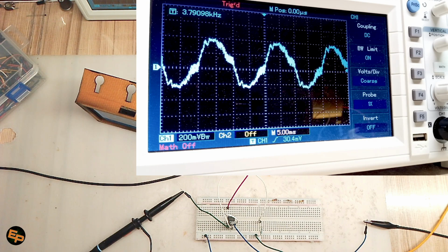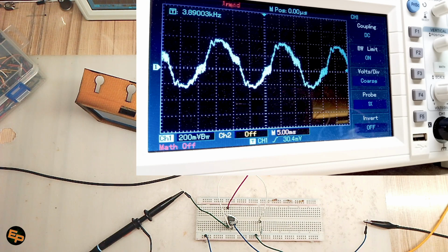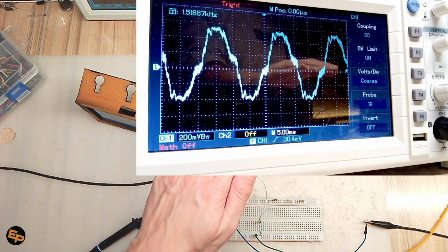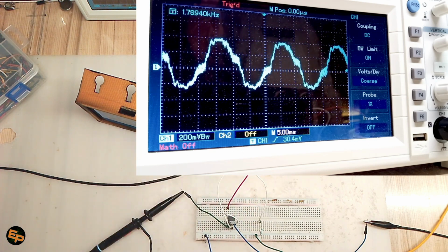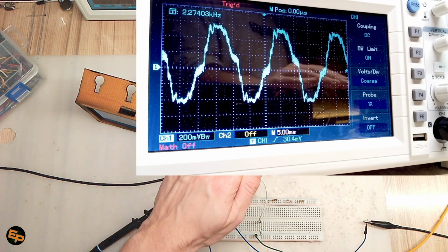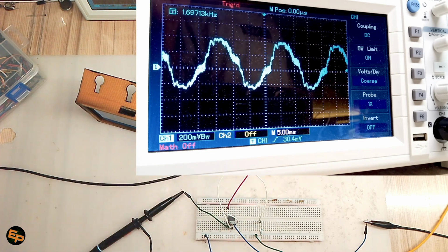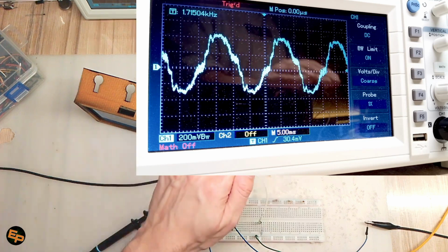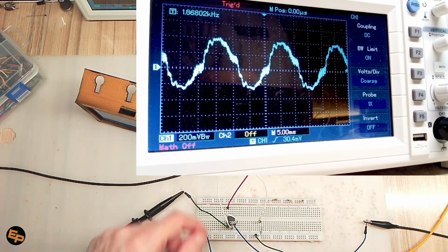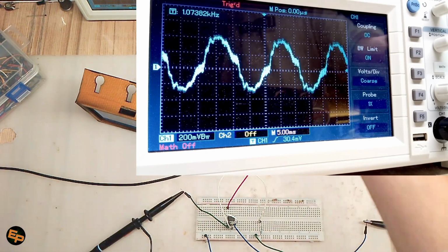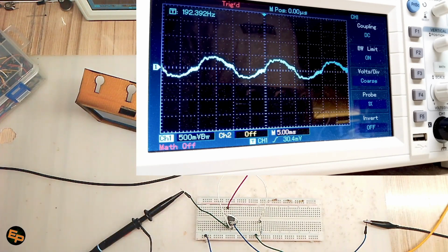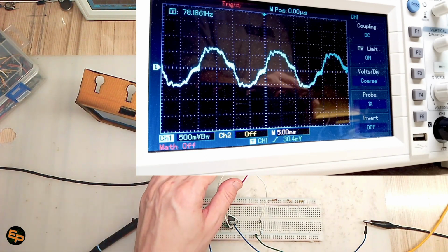So what I want to show you here in this video is that I was at some point just bringing my left hand closer, or taking it farther away from this cable. Initially I wasn't touching the cable, and as you can see, this unwanted signal gets bigger the closer I get, because my body basically works like an antenna.